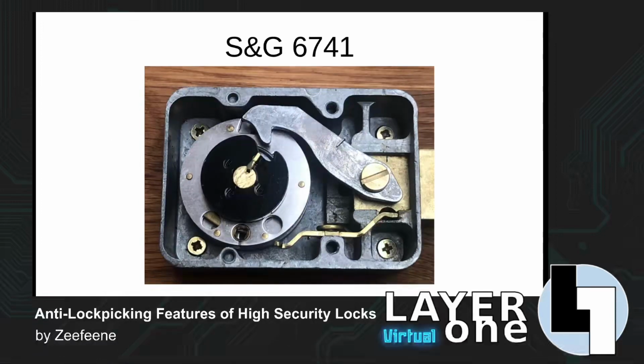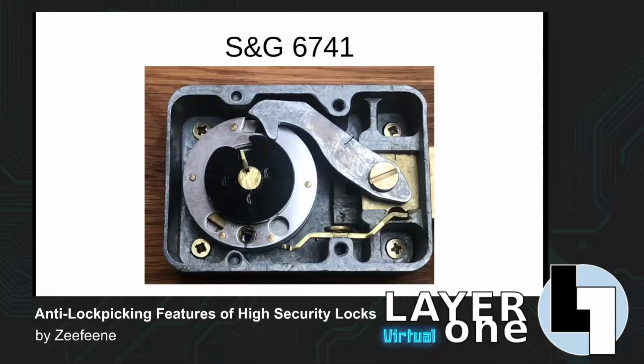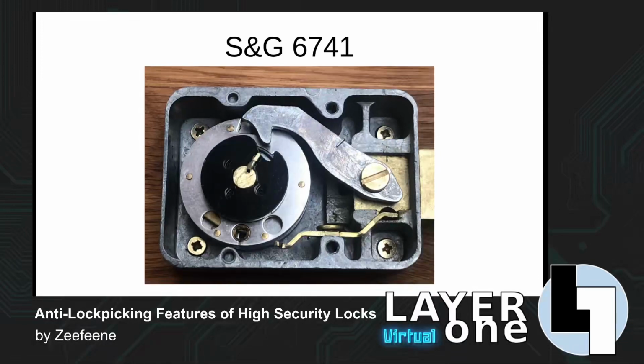this black portion moves 1-to-1 with the dial, and it's necessary to move that before you can move any of the wheels. And so the problem is, in this position, the nose drops in slightly, because it has space, it matches the gate in the drive cam, and so at this point we have tension against the wheels, but anywhere else that we move this drive cam, the drive cam causes the nose to lift up, or the lever to lift up, and at this point there is no contact against the wheels, and so there is no way of tensioning the mechanism unless we are inside that little gate in the drive cam.